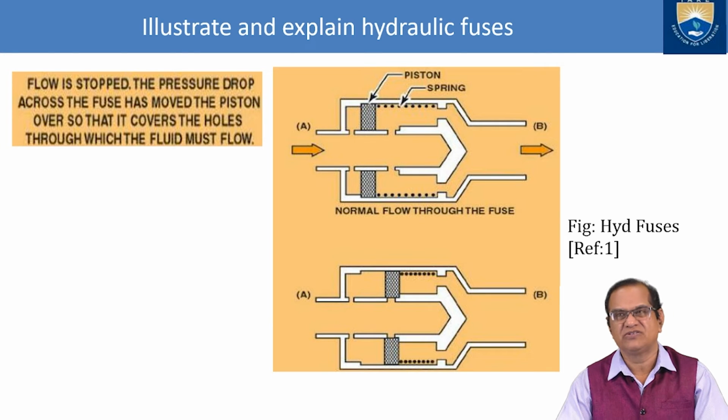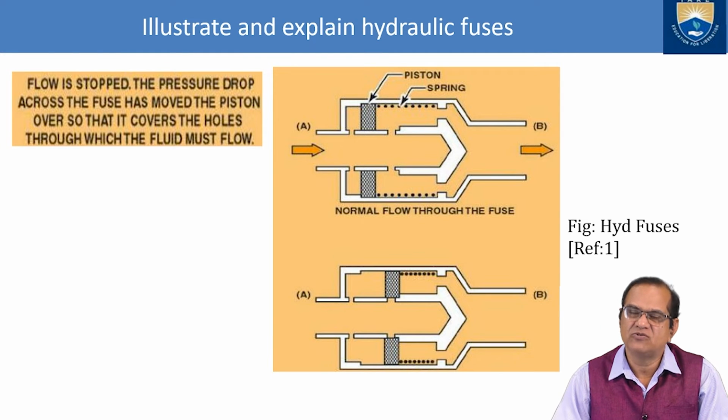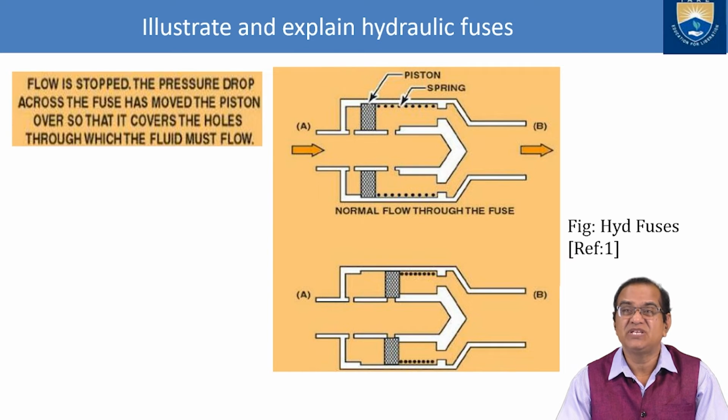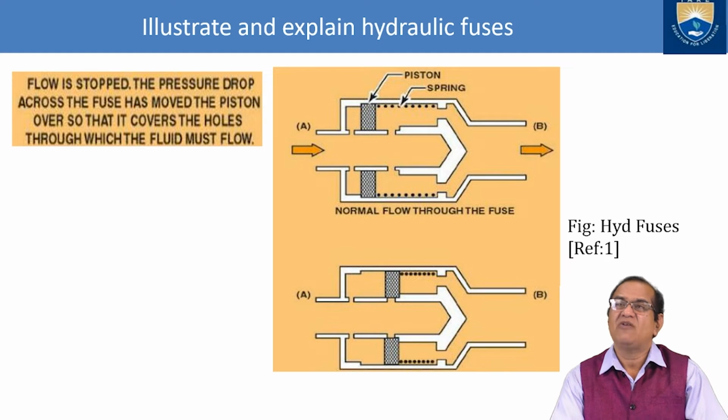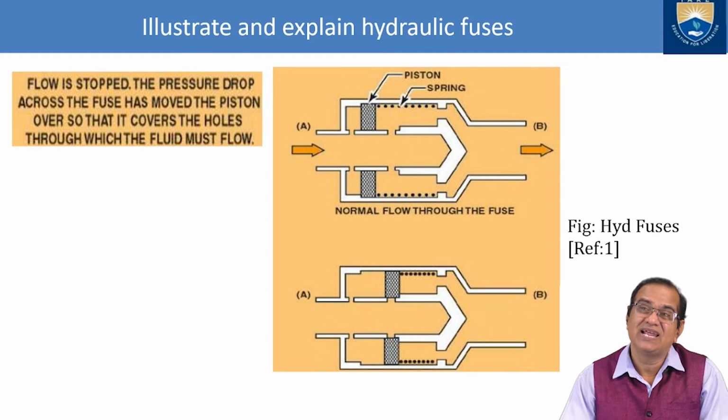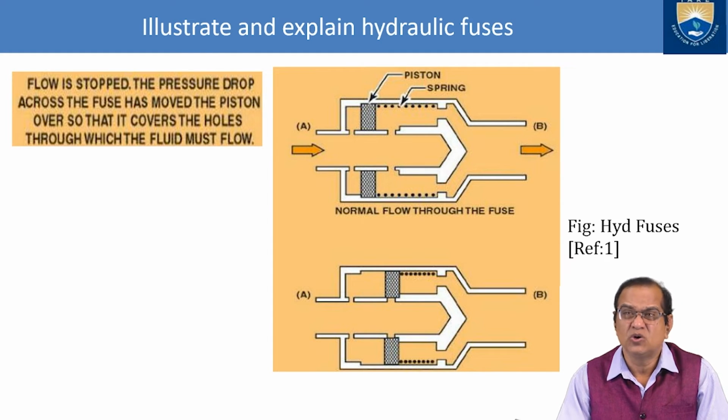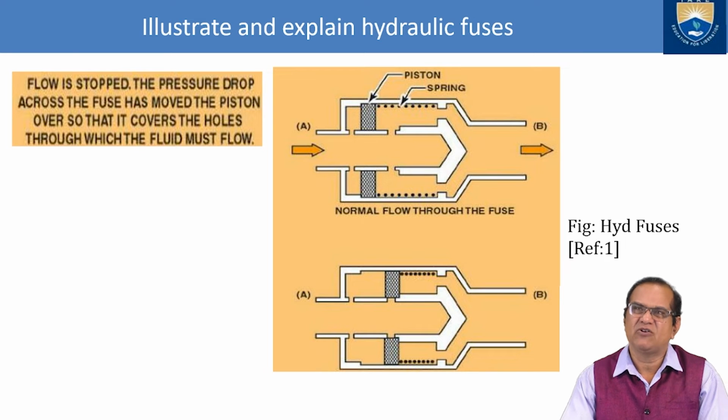In the same way in hydraulic systems also, we have to make sure that as and when the system pressure is going above the required amount, what will happen? There is a chance of bursting of the system, the pipeline may burst, leakage may be more, and your seal may be damaged. To avoid that, our system should be within the given limitation. That is the purpose of any hydraulic fuse.